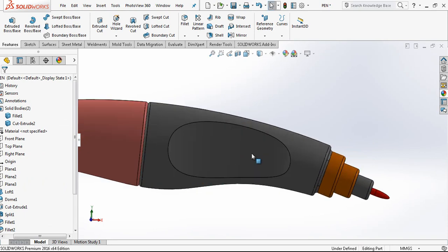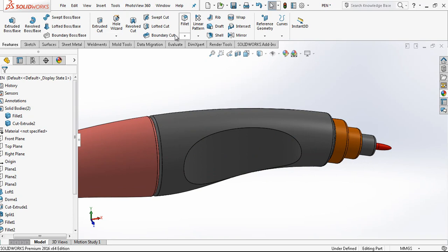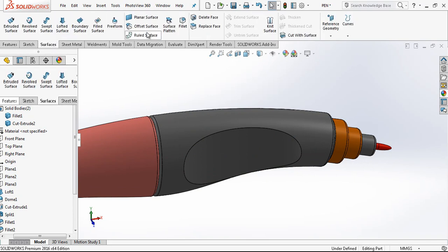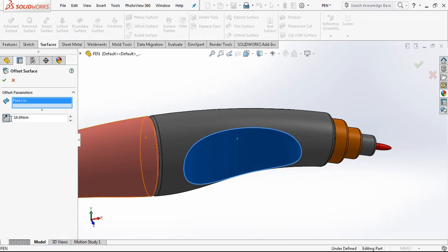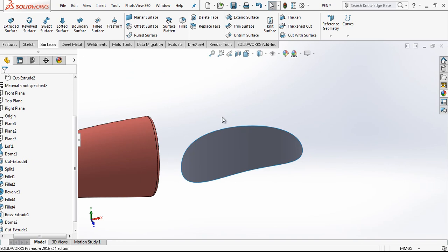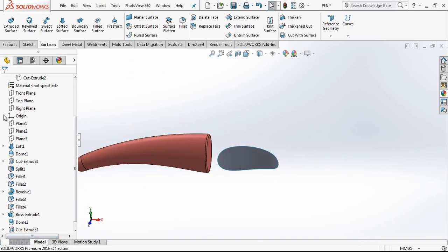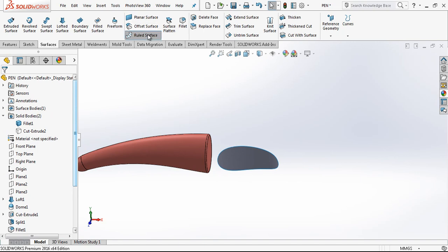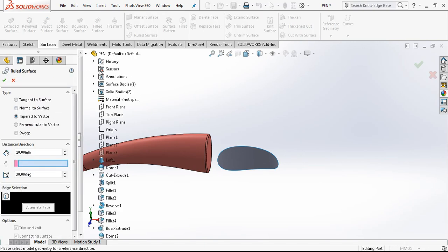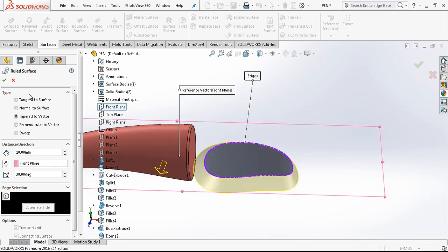Yes, it is not looking so bad. At this point I'm satisfied with the value. We are not changing it. We are making an offset, 1.5mm deep offset back, and we create a surface here. Now with Revolve Surface we are going to create some flanges around this.